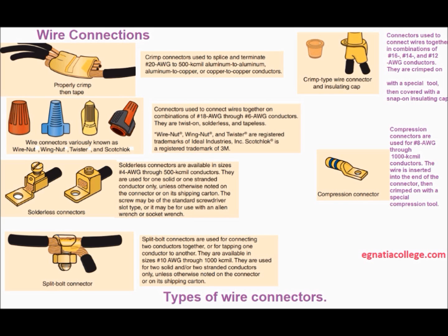Solder-type lugs are not often used today. In fact, connections that depend on solder are not permitted for connecting service entrance conductors to service equipment. The labor costs make the cost of using solder-type connections prohibitive. Solderless connectors, designed to establish connections by means of mechanical pressure, are quite common.